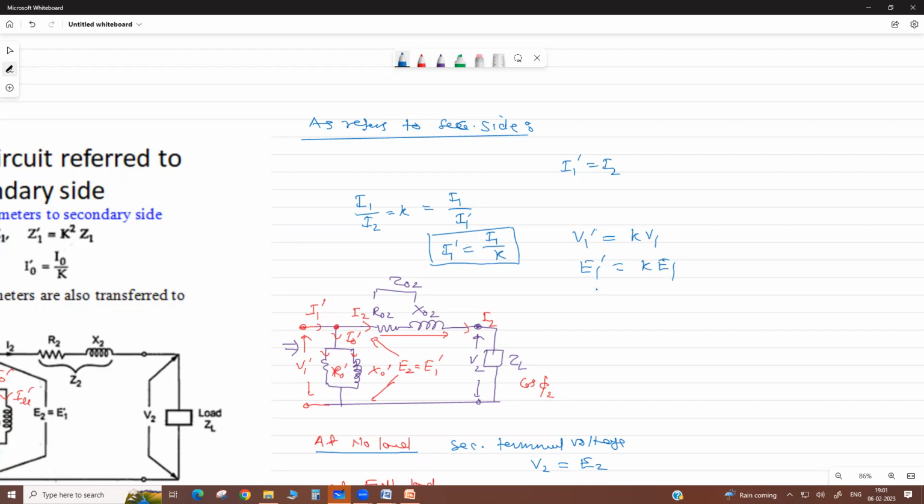Okay, dear. Now we come to your resistance and reactance. Now total copper loss as referred to secondary side: total resistance R02, current I2 squared equals total copper loss in individual windings, R2 plus I1 by I2 whole squared into R1.